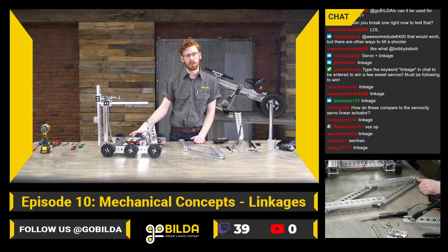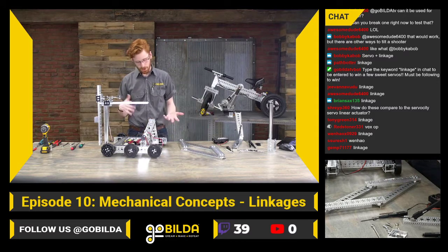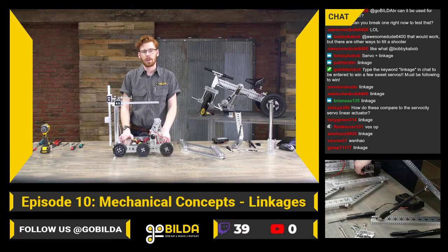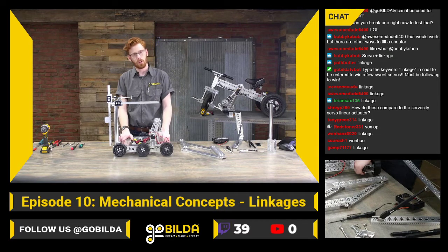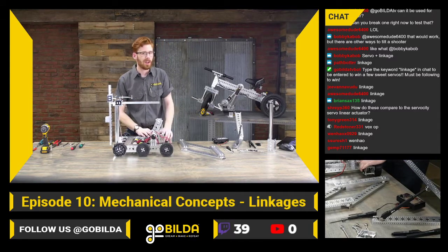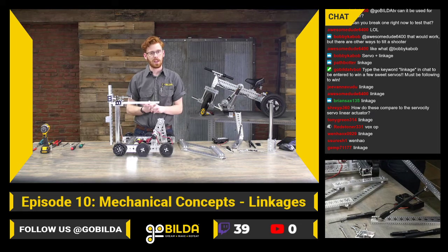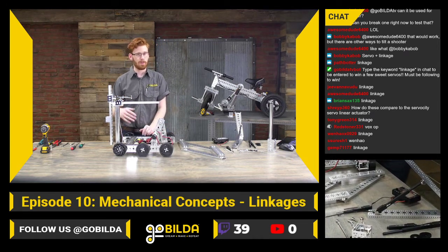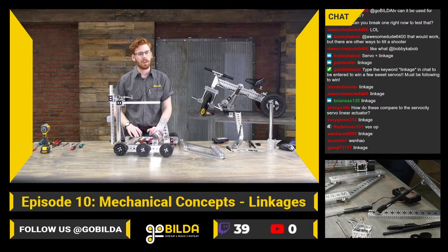Sometimes, depending on what you're looking at, servos can vary a little bit on their ratings. A great example is, in my experience, Hitec ratings are pretty conservative, and something like a Savox is going to be rated right at what you'll get out of it. So even though you might have a Savox on paper that performs better, a Hitec might be able to push more power through it in the real world.